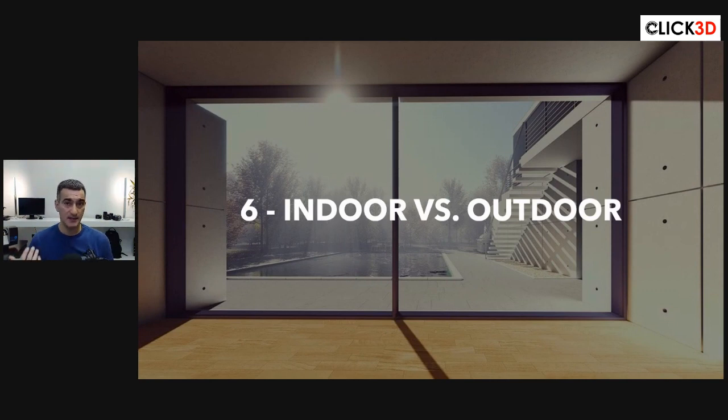Whereas the photogrammetry, or the camera with photogrammetry, doesn't like to be in a fixed position and then just kind of rotate around that position. It needs to move its position around the object. It does better when you do it that way. Now, if you're doing 360 images, again, you can be in one spot, but you can't just do one 360 image. You need multiple positions. And again, it's that issue of being able to move around. So from this perspective, indoor versus outdoor, laser scanner has a little bit of an advantage here. Let's move on to number 7.